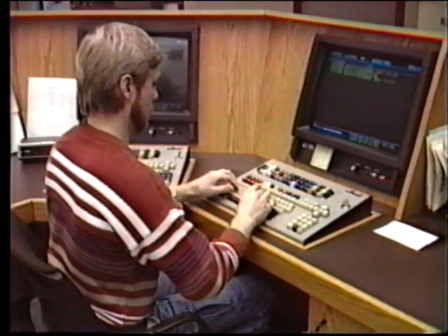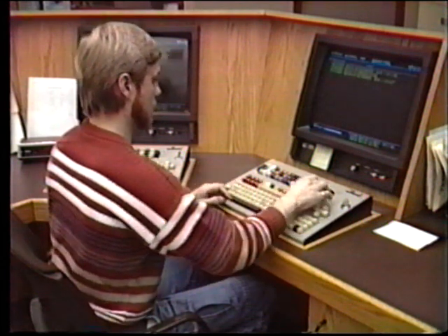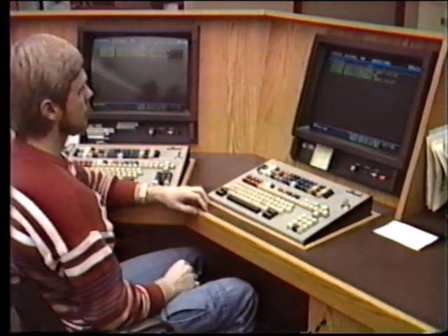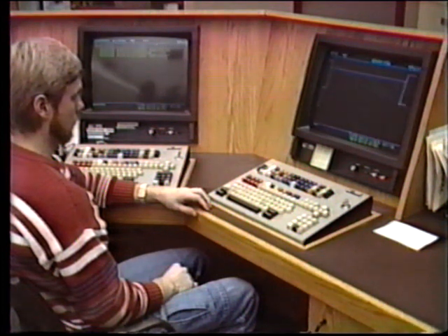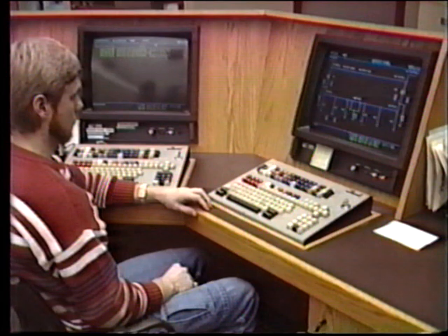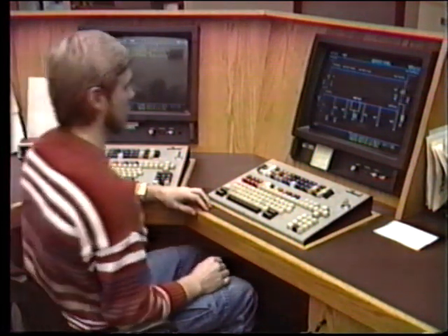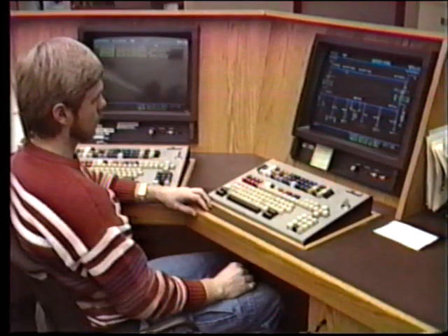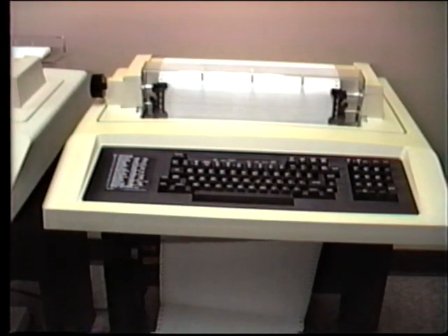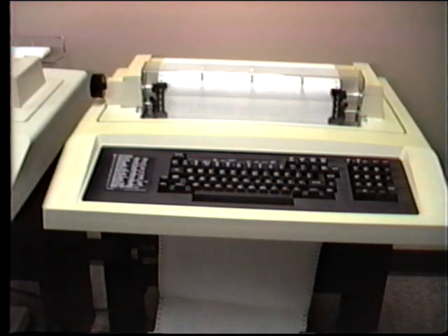The operator interacts with the central computer through the CRT terminal. This can display selected information related to any part of the system under his control. For example, he may want to see a scan of all points at a particular RTU instead of exceptions only. The operator can also instruct the computer to print out selected information to assist in operating or contingency analysis.